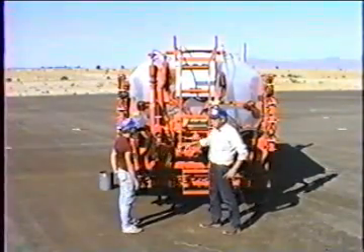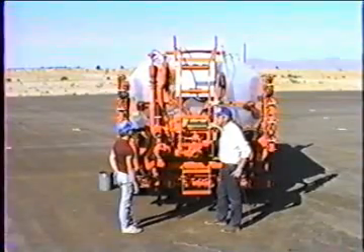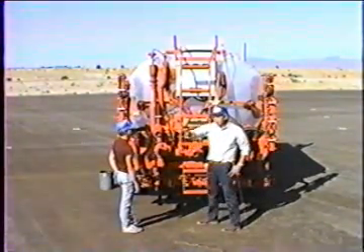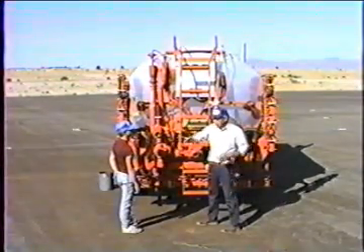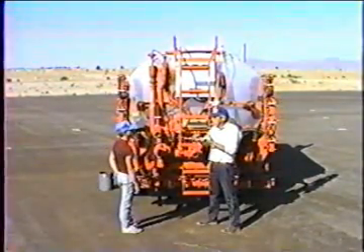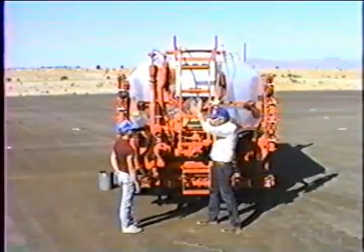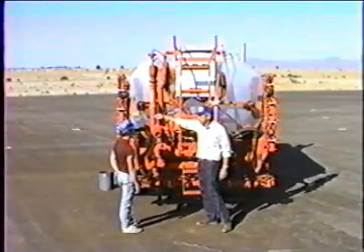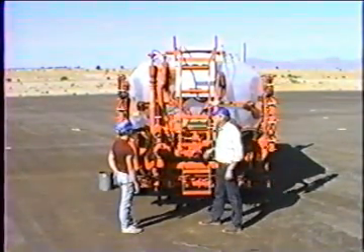Okay, we've pumped off or filled this up, whichever occurs first. It's time to stop loading, turn off the trailer valve, disconnect the hose, loosen it up a little bit and let some air into it so it doesn't gurgle a bunch out. Disconnect the hose, drain the hose, just hold it up to where it drains down into here. Now close this valve. Put your hose away and get back in the cab of the truck.